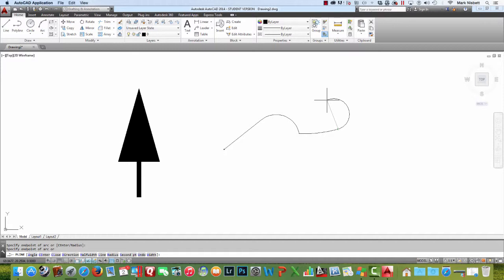Center can be quite useful. So say, for instance, I want this arc to go around the center point of this arc. I could type in CE for center and come down here and pick that center, and notice that that arc is now coming like this across here like that. So I could do that sort of thing, and then I get my tangent arcs again.